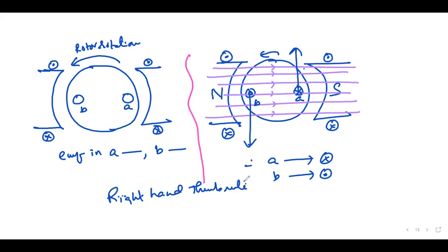Current is inwards here, and outwards there. Therefore it will give the flux in this direction, and that is the reason it is a north pole. The other one is receiving the flux, so it acts as a south pole. The examiner simply gives cross and dot data to check whether the student has an idea about the application of the right hand thumb rule.